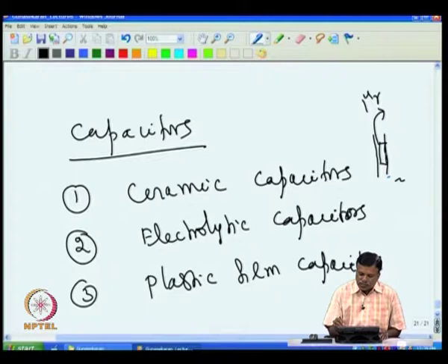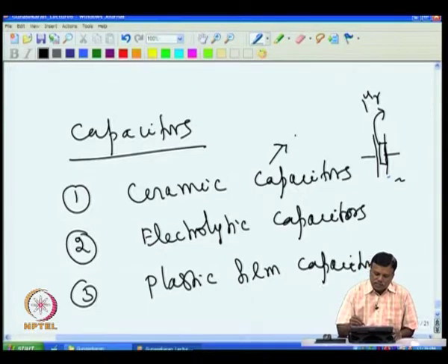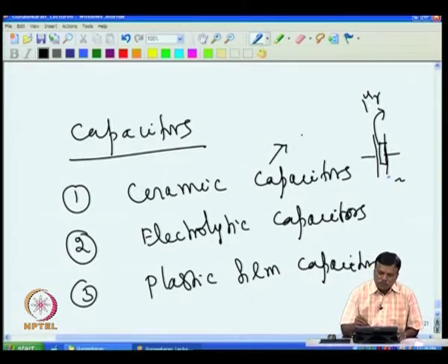The net result is you get the capacitor without the inductance. So, this ceramic capacitor is the one which gives you the capacitance value with almost no inductance, or very little inductance. So, wherever we need capacitance with less inductance, one can go for ceramic capacitors.